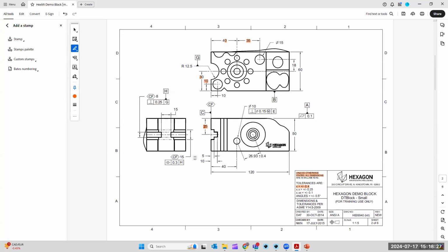So to do that, we have to build the two surfaces that are on either side of it and then construct the actual center line. Then we can go from that center line to datum A and compare the dimensions to 25 with a tolerance of 0.4 plus or minus. So that's where we're going to get today, okay?